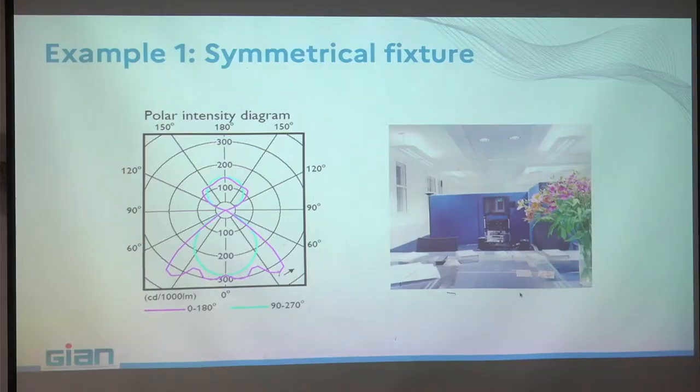Examples to understand here. I want to have uniform lighting in the working desk. Here is a configuration of cubicles that you can find, for example, in the US or in Japan. And you have also a corridor here, and people have to walk. Look, here we select the fixtures.